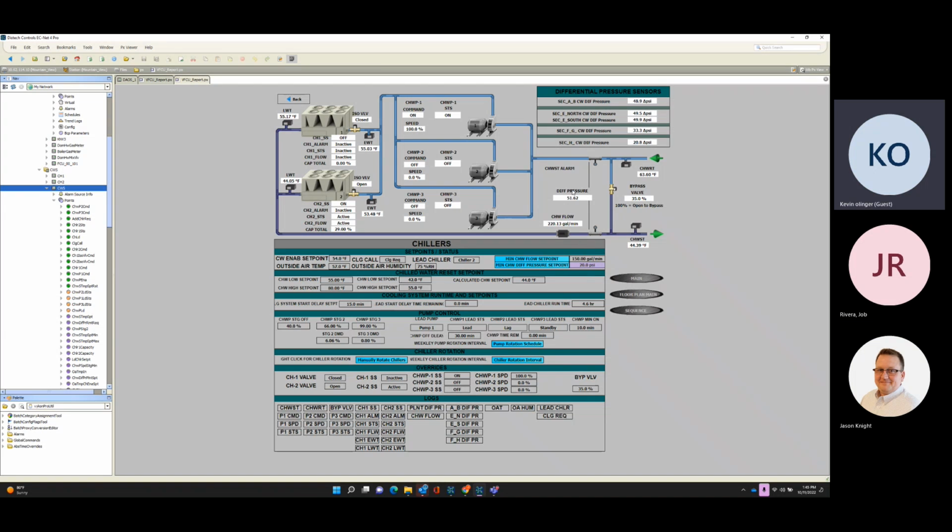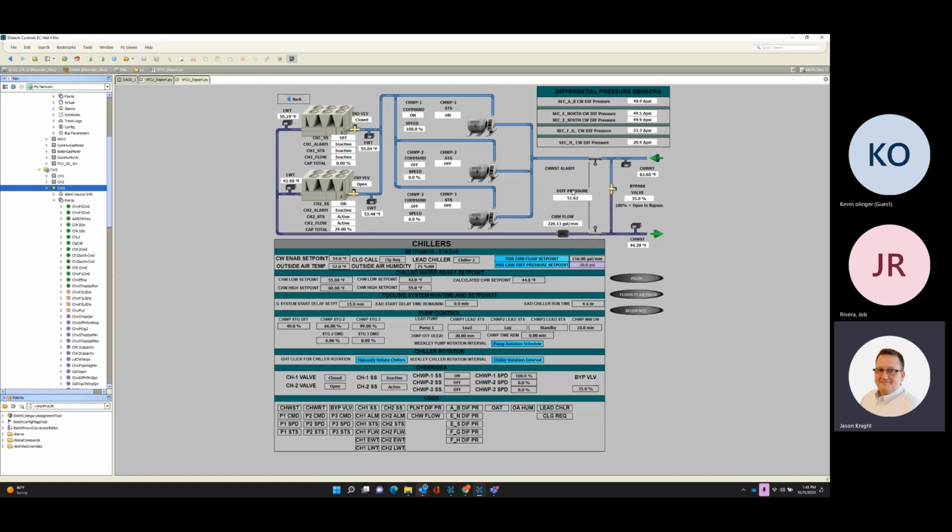But instead of having the logic of, we're going to maintain a minimum of 20 pounds differential in any of your zones you have listed up above, and you must maintain a minimum of 150 GPM, and if we drop below either one of those, pumps ramp up to maintain. That's why, when I go back to the engineer, I'm like, okay, well, pick your battle. Which one do you want me to do? Because they'll describe all 3 sequences and tell me to control all 3 at the same time. It's like, well, that's not how that works.